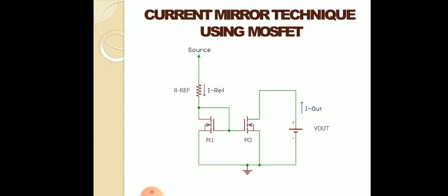Okay, for the case of MOSFET M2, it will also remain in saturation mode as long as the output voltage is greater than the saturation voltage. Therefore, the input current across M1 will directly control the output current of M2. Actually, the MOSFET device functions like this: the drain current reflects the function of the gate to source and drain to gate voltage.